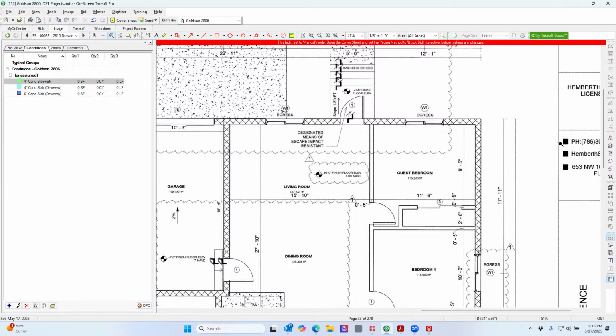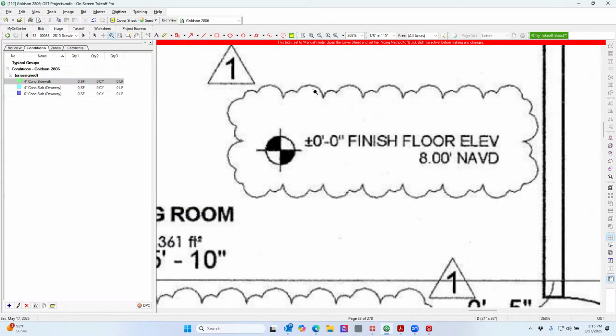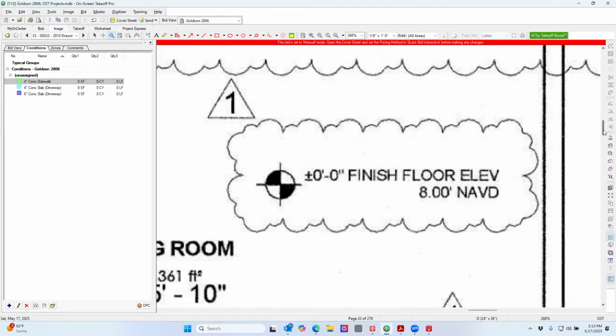Well, here's one thing I think is interesting. Remember, earlier this week we were talking about reading elevations, and Doc, you had some questions about actual exterior elevations versus floor elevations, meaning height. Look at this. This is something you'll have to get used to. Sometimes the engineer will show the finished floor at 0, sometimes it will say 100, and sometimes it will say the actual elevation, like 106.5. What you have to do is decide where everything else is. Normally when they use 0 or 100, that's the baseline, the starting point.